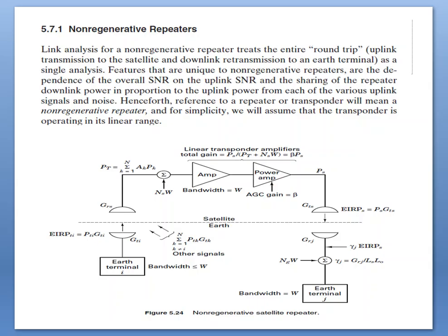Now coming to the second part, non-regenerative repeaters. First we discussed the regenerative repeaters and now we go for the non-regenerative repeaters. Link analysis for non-regenerative repeaters treats the entire round trip, meaning uplink transmission to the satellite and downlink retransmission to the earth terminal, as a single analysis.